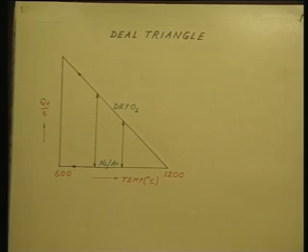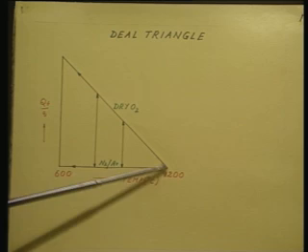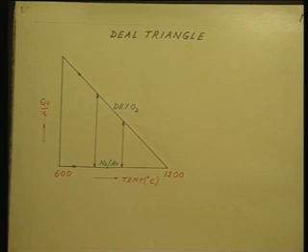So, this is actually depicted here in this figure. This is called the Deal triangle, named after B.E. Deal, who was one of the pioneers in the silicon dioxide oxidation process. What we have here is on this axis the fixed oxide charge QF by Q. This Q is electronic charge, so it is a normalized value. And on this axis we have the temperature. So, you see from 600 degrees centigrade to 1200 degrees centigrade, that is the scale.